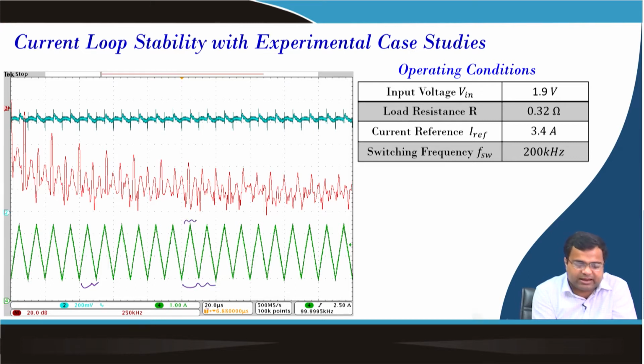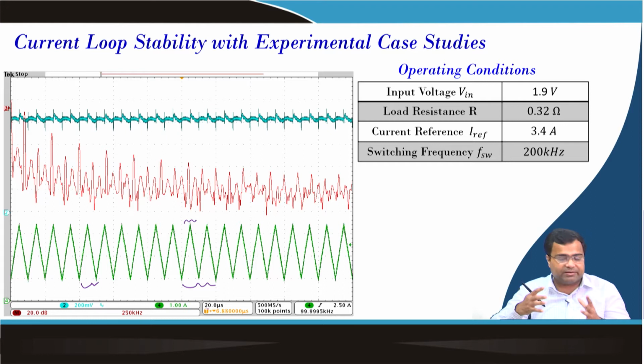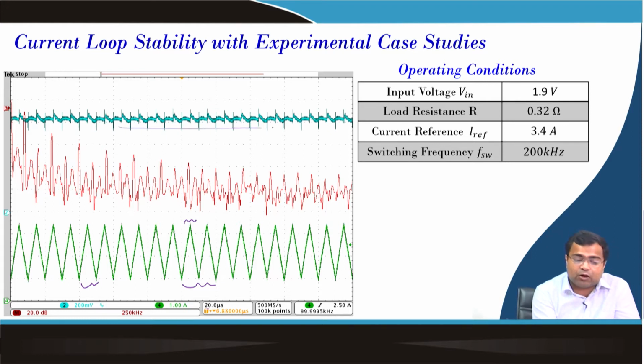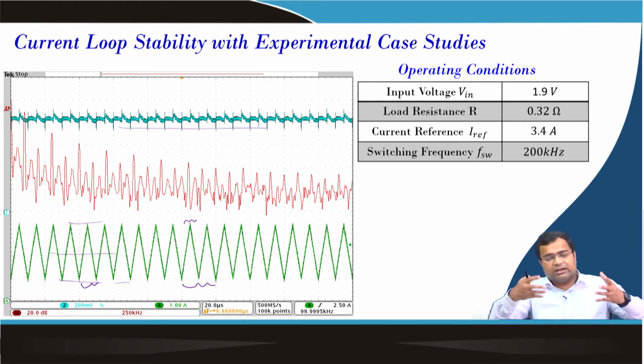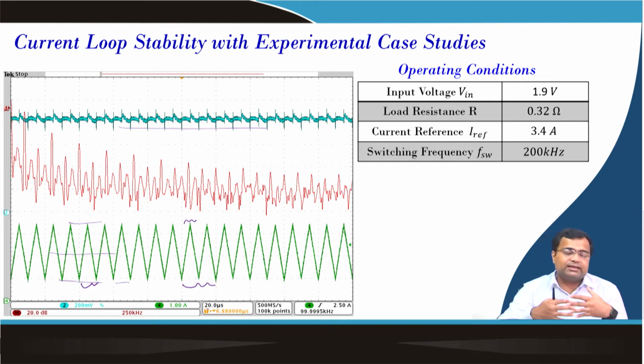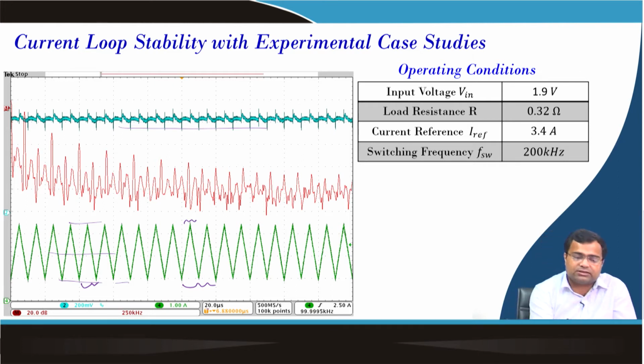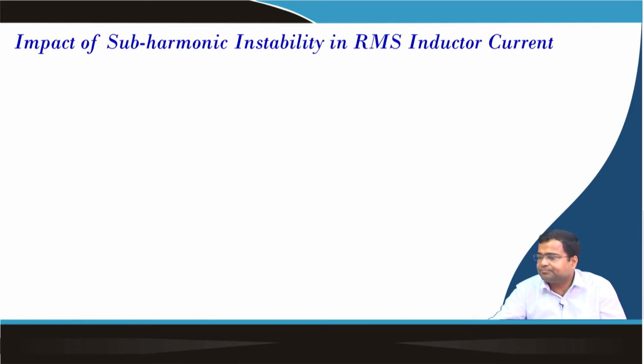So, this should be 10 microsecond, but we have 5 microsecond, 200 kilohertz switching frequency, and this is because of nonlinear phenomena. You can see that the output voltage also goes down, because your peak current is fixed. So, this is going down, so the average will go down, and as a result your average voltage. So, you need to anticipate, this can be regulated by an integral control, but this instability can cause a large ripple current as well as voltage.